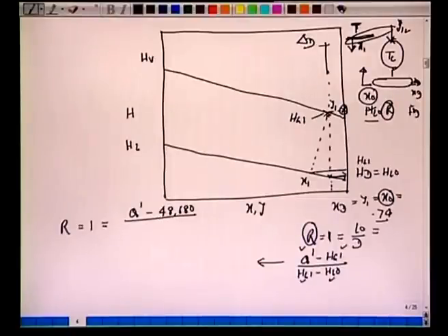So this is HG1, and we have HG1 minus HL0, 48,680 minus 39,830. So the liquid which is saturated at this condensation temperature, enthalpy is HL0, 39,830, and this vapor which is saturated at this temperature, their enthalpy is 48,680.